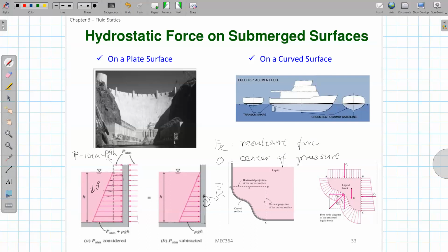Oh, okay, so it's just to denote the pressure increasing in the vertical, not the horizontal. Yeah. Thank you. So that's why it's starting from here, and this line here is still 1 atmosphere. So you can balance it with 1 atmosphere on the other side, remove this one, and the net force will be just equal to this triangle profile.